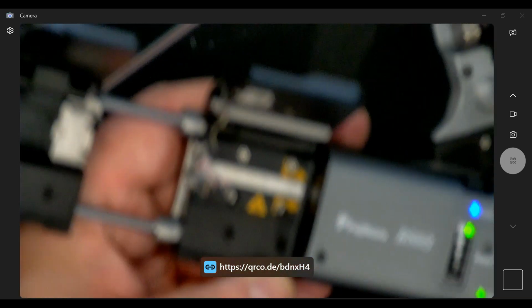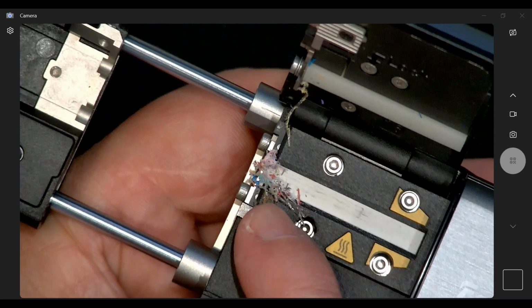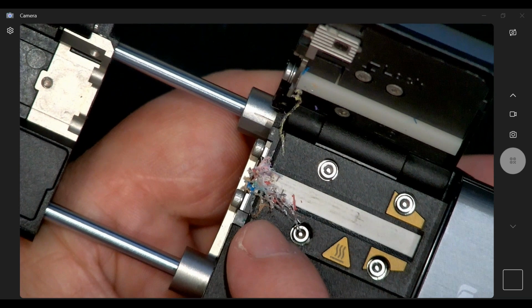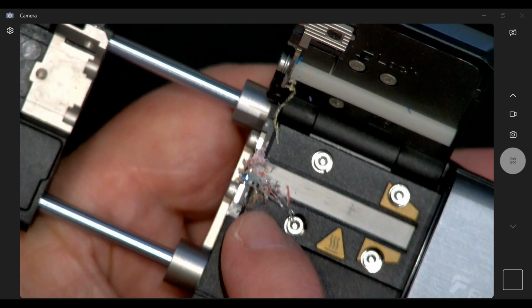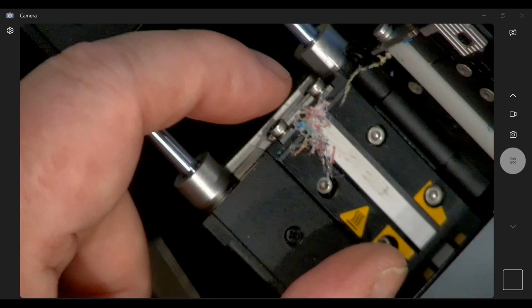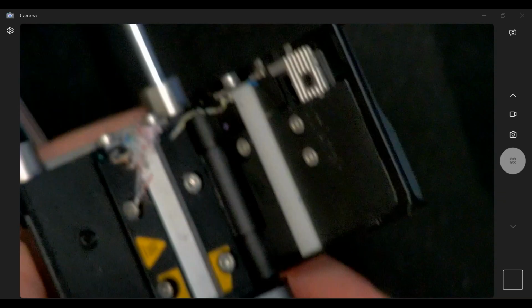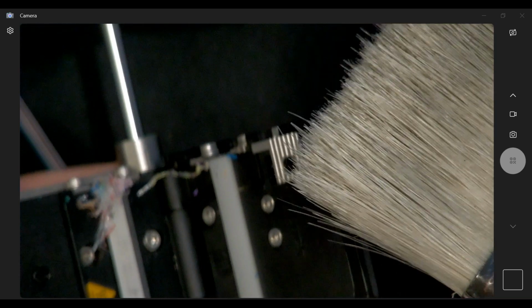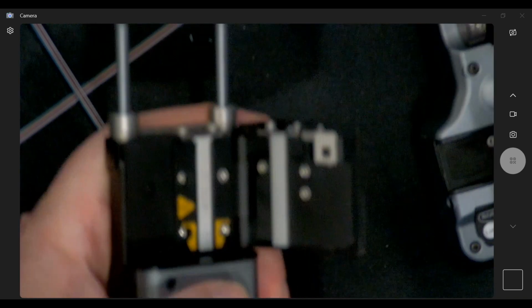Thank you, Mega. You'll notice here the coating that has backed up the side of it. This is if I do loose tube fiber. This is if I do rollable ribbon. If you're doing traditional ribbon, it will come out as a complete matrix, and you can discard that very easily. By the way, this is a nice tool for this purpose, to clean the debris out of your hot jacket stripper.